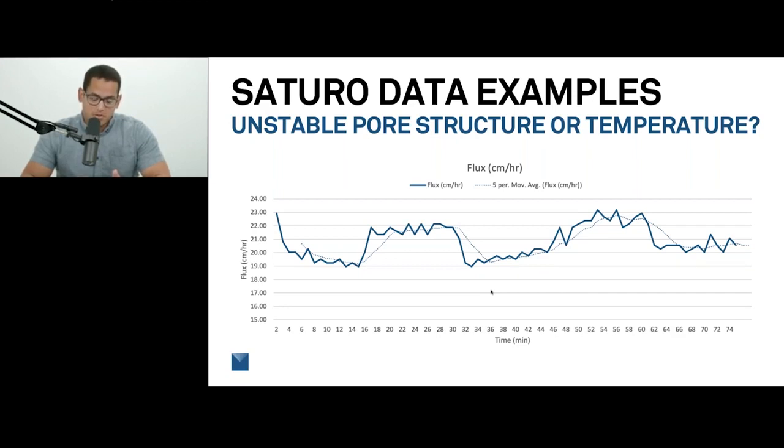But taking temperature measurements of your water, taking antecedent soil moisture measurements, and taking soil temperature measurements as well, because these all play a role in the end result that you get in your hydraulic conductivity values. So I always highly encourage taking as much metadata as you can, even site assessment pictures, the more metadata, the better. So another good example of just some steady increases.